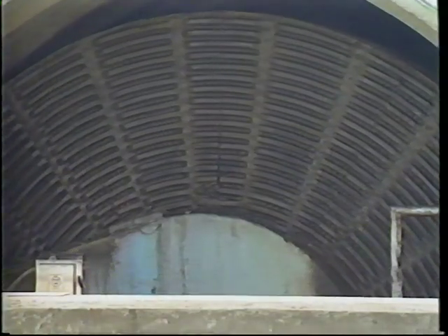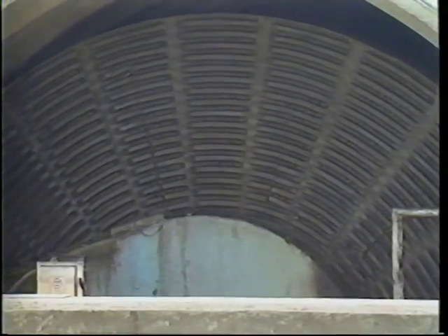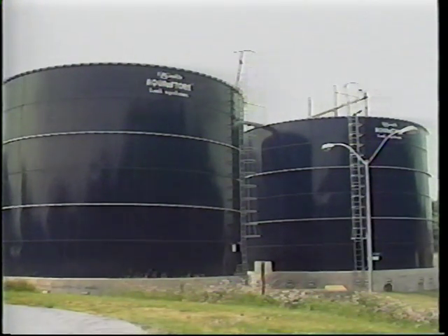pollution. Trickling filters and rotating biological contactors are carefully controlled biological processes that utilize aerobic microorganisms to consume colloidal and dissolved organic matter from the wastewater. Removal of the colloidal and dissolved solids is necessary to reduce the BOD in the wastewater. In some cases, trickling filters and rotating biological contactors are designed to remove ammonia from the wastewater.